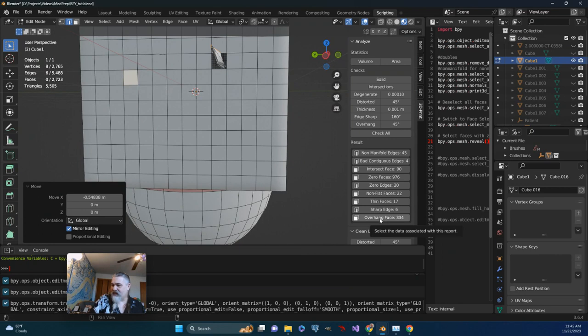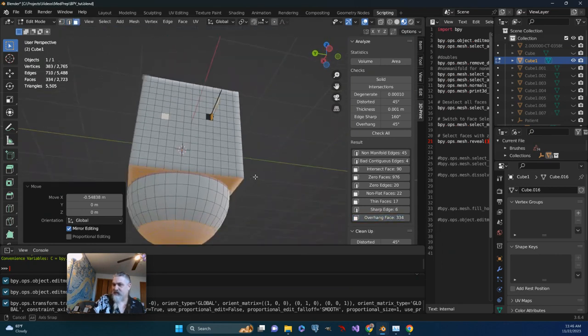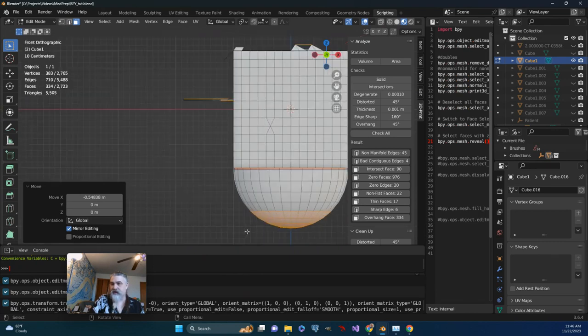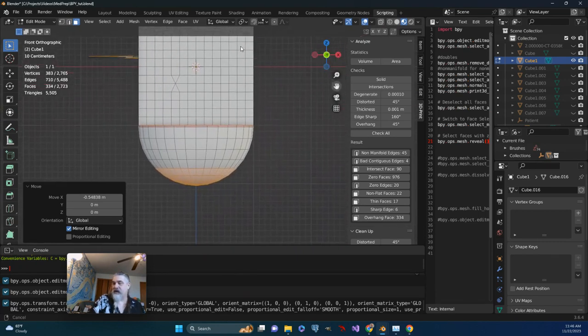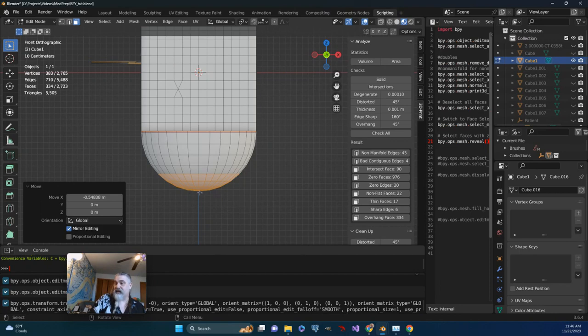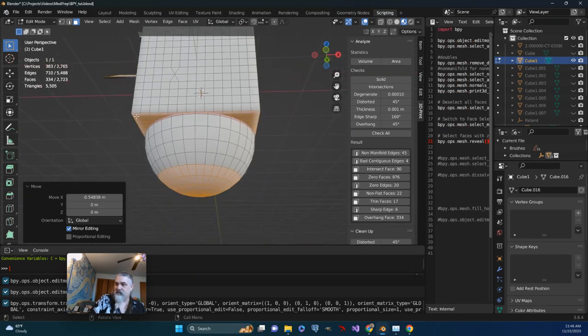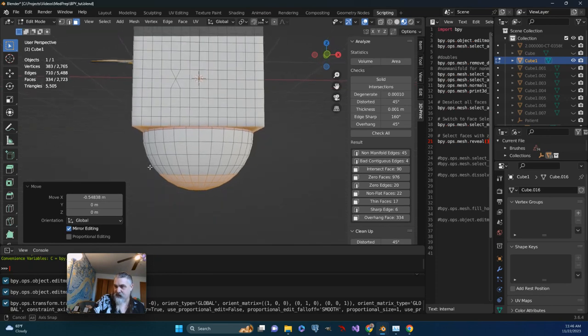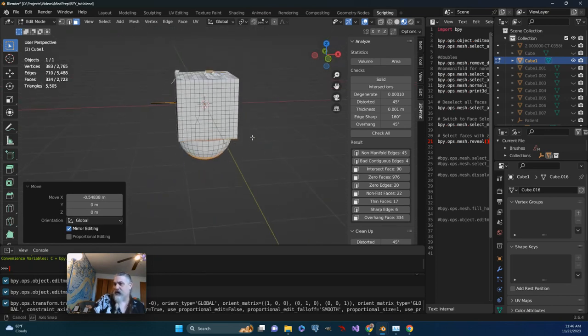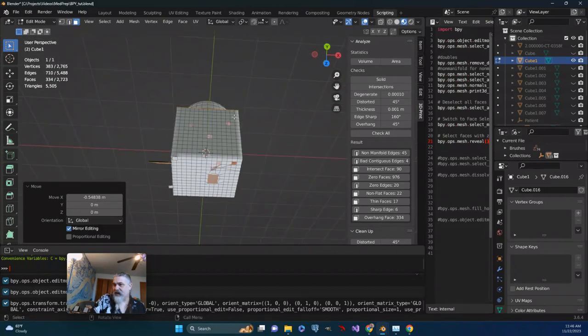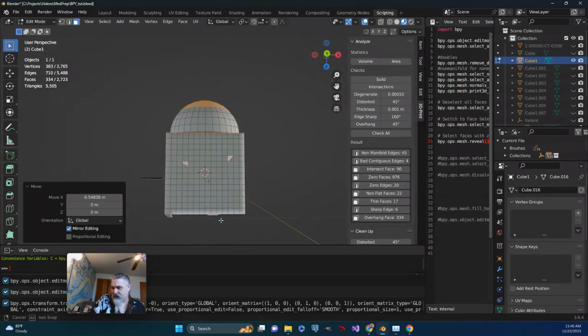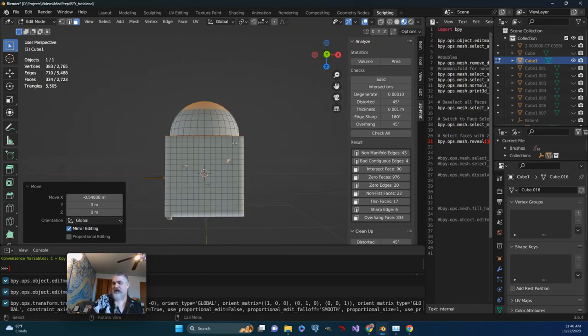So lastly, overhanging faces. Well, if we click on this, we can see what's happening here. Let's imagine that I'm printing this thing, 3D printing, and I've got it sitting on the build plate like this. Well, you're basically printing over thin air as your extruder moves up. Likewise here, it's printing over completely thin air. It's got nothing to attach itself to. Blender doesn't know how you're orienting this thing. It may well be that I'm printing it this way, without these faces that I extended down that I was just messing around with. In which case, these overhanging faces become a non-issue up here.